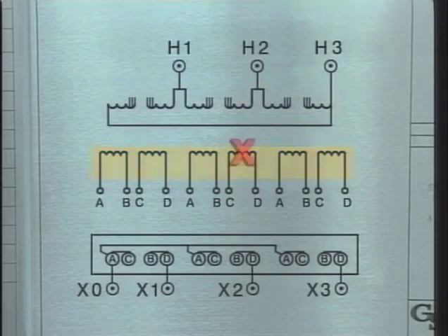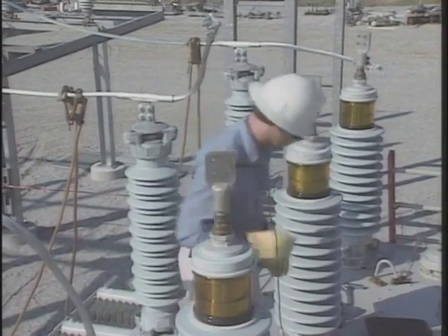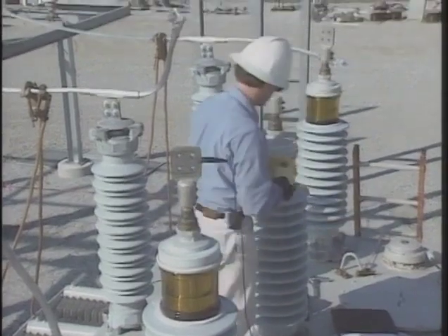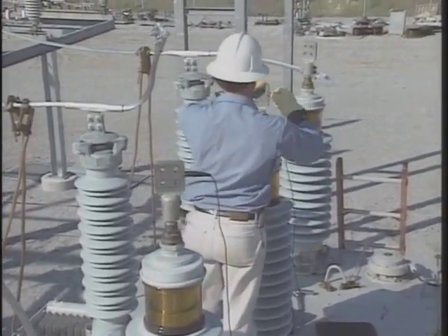If for any reason a winding is damaged, shorted, or isolated from the circuit, the transformer will not provide the desired output voltage. And in the case of winding damage or a short, continued use of the transformer could result in major transformer failure. To a degree, winding problems can be detected while they're still minor by a test known as the transformer turns ratio test.